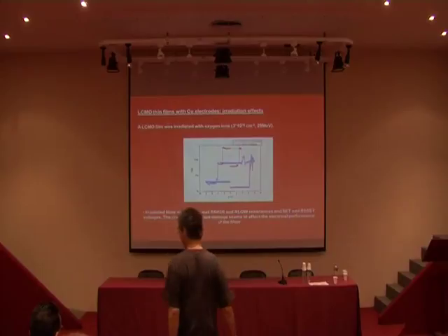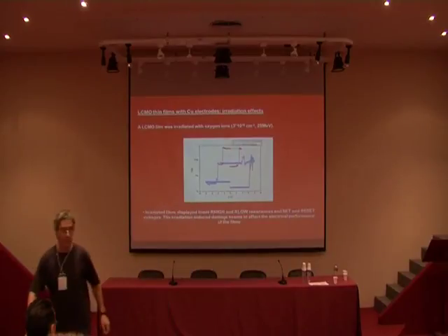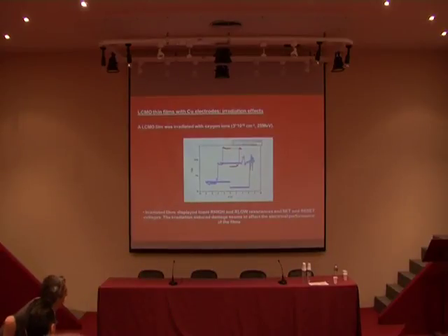Please explain to me what's happening there. Is the current constant as you're sweeping the bias? Sorry, I think I didn't say, it's the hysteresis switching loop. It's the remnant state. But for each voltage, the current is the same. But we are applying a small reading voltage of 100 millivolts. It is not the dynamic IV curve.